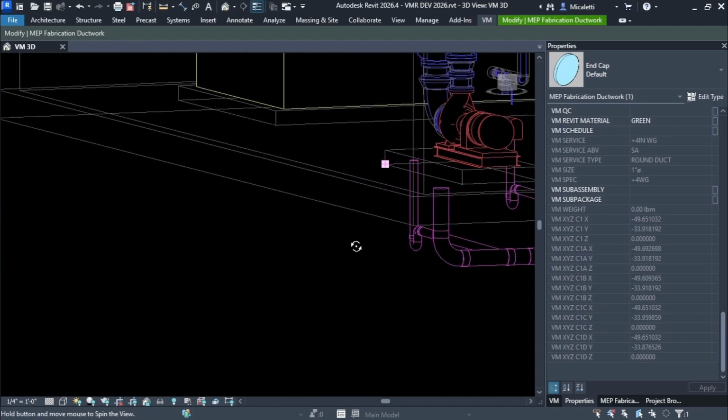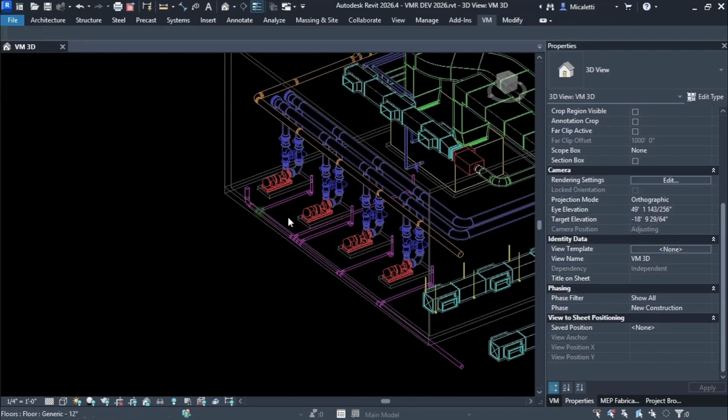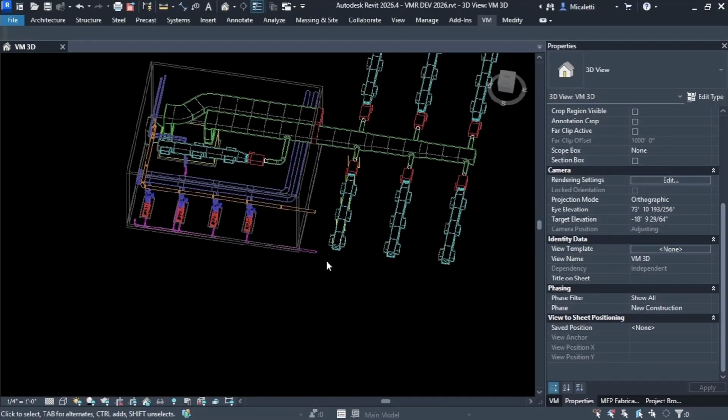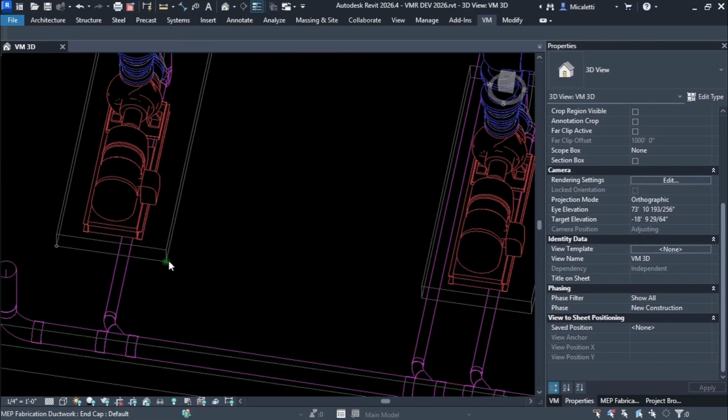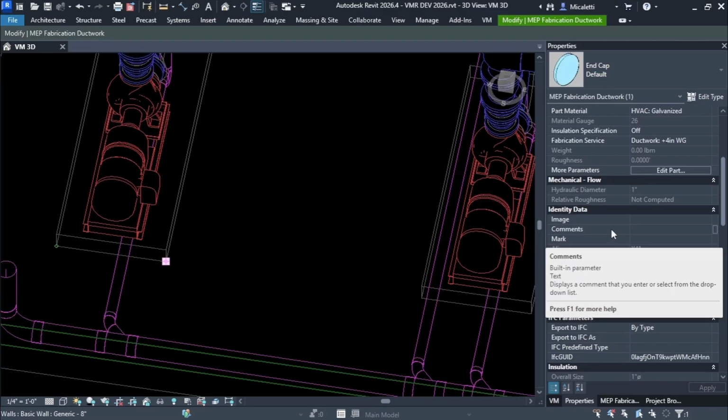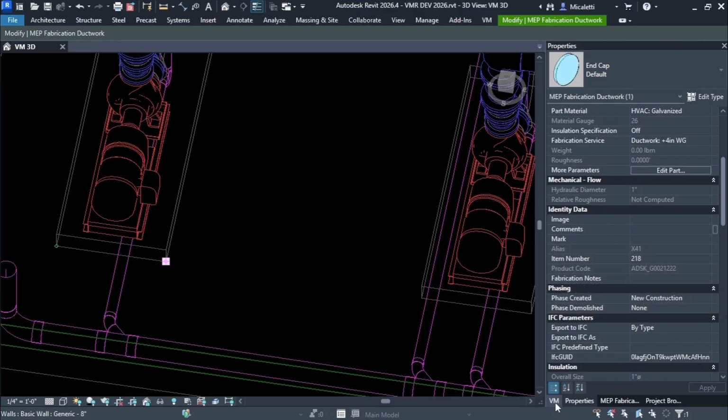And if you wanted to, our field teams can be kind of particular about the descriptions for a given point in the exports we give them. So if you wanted that white center point that lines up with the corner of the pad to have a description like pad corner, where's the parameter or VM parameter to put in a custom description? Good point. You could make a parameter that applies to fabrication parts, or if you're using families, you can make a parameter that applies that, and then whatever they want.